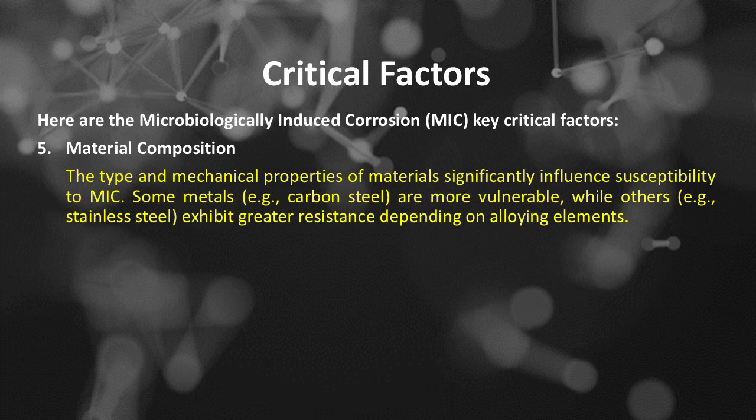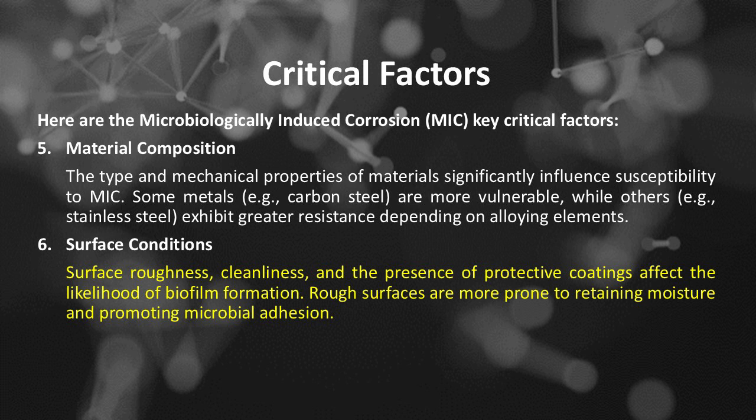Number 6 of the microbiologically induced corrosion, or MIC, key critical factors is surface conditions. Surface roughness, cleanliness, and the presence of protective coatings affect the likelihood of biofilm formation. Rough surfaces are more prone to retaining moisture and promoting microbial adhesion.